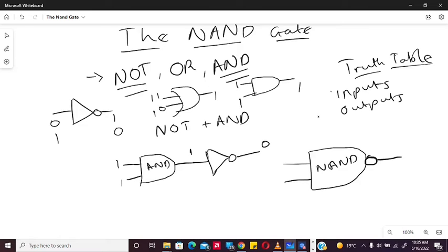There's actually a rule in determining what kind of inputs or input pairs a logic gate can get, and that is 2 to the power x. What do I mean by this 2 to the power x? Look at this NOT. What input set or what kind of inputs can it get? It only takes in one input. The x is actually representing the inputs that a logic gate can get. So it takes in one input, and that will be 2 to the power 1, which will go to 2. So this 2 is representing that this NOT gate can take a 0 or it can take 1. It can only take two distinct inputs.